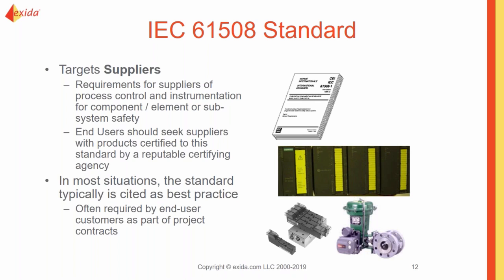In the standard, it's going to define the concepts of SIL, of SIF, of SIS, and we'll talk about what all of those mean. And it also talks about having some type of functional safety life cycle. It does give an example, but you can use any sort of safety life cycle and follow that approach. And that's how you're going to get rid of those systematic design errors.